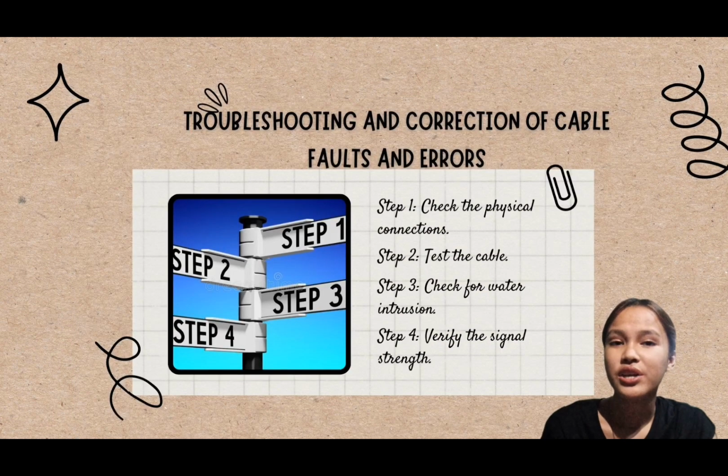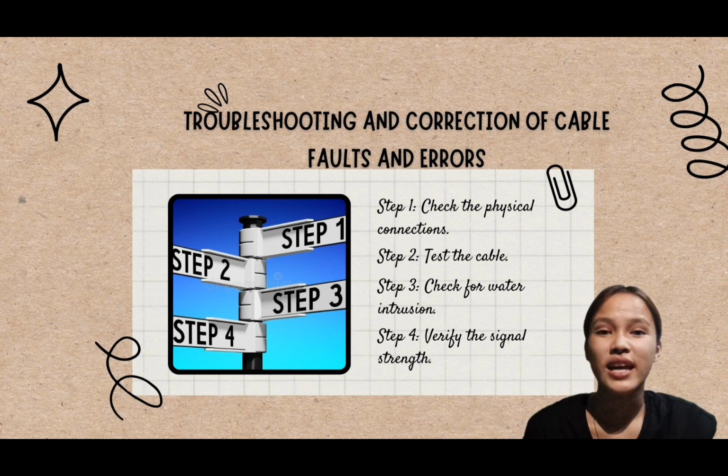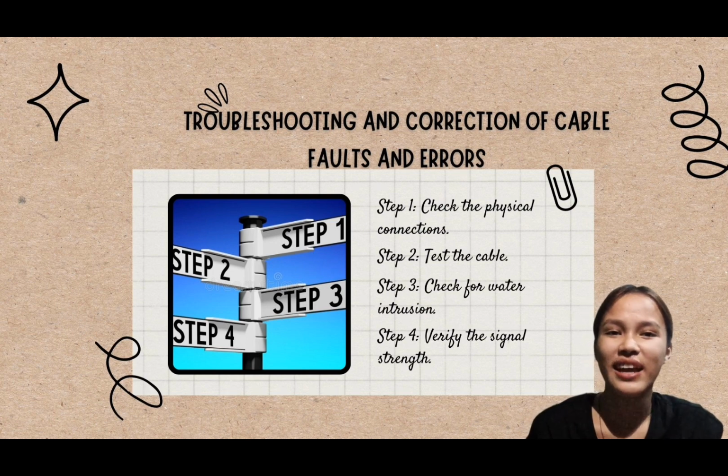Step 1. Check the physical connections. Ensure that all cable connections are secure and not loose. Check for any damage to the cable or connection. Step 2. Test the cable. Use a cable tester to check for continuity and any shorts or breaks in the cable.